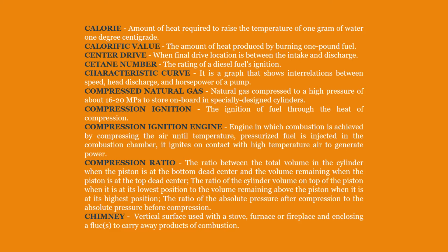Compressed natural gas. Natural gas compressed to a high pressure of about 16 to 20 megapascal to store on board in specially designed cylinders. Compression ignition. The ignition of fuel through the heat of compression. Compression ignition engine. Engine in which combustion is achieved by compressing the air until temperature is high. Pressurized fuel is injected in the combustion chamber. It ignites on contact with high temperature air to generate power.